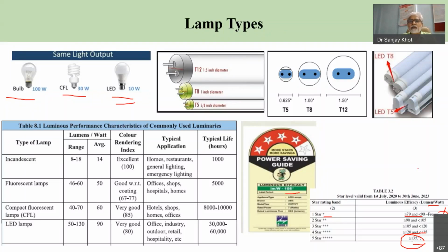Now here is what I already mentioned about the power analyzer. If I use the power analyzer to read the consumption of this tube light, it shows that this tube light is consuming 43 watts of power. This is 0.043, that means 43 watts of power. And this is the total detail about the power analyzer, the photo.